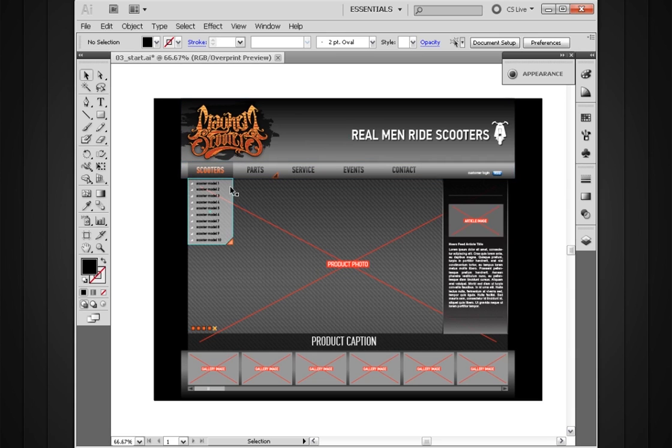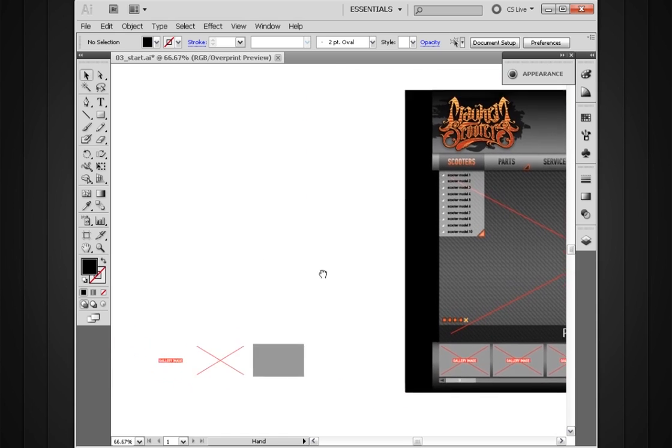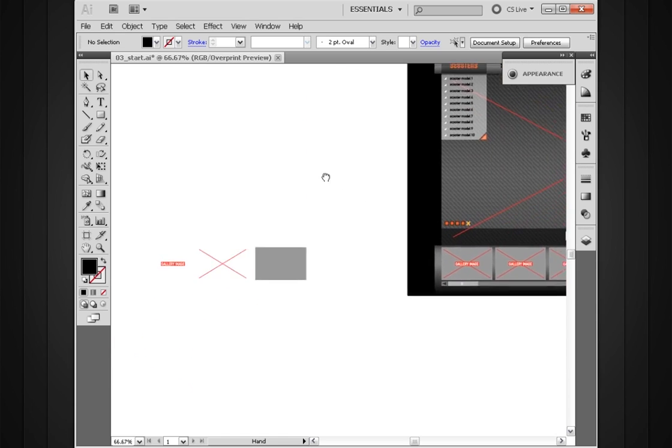So with the smart guides turned on, you can see here that as I mouse over my objects, a number of things are happening. We're getting outlines around some of the objects. We're getting a little gray window with some coordinates popping up, and we're also getting some little green words that are popping up in places, saying things like anchor and path and center. So there's a whole lot going on here. And maybe for your purposes you don't need all this information, but the great thing about smart guides is they're highly customizable based on your personal needs as a designer.